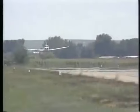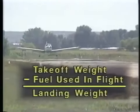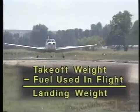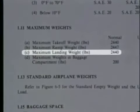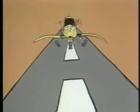An airplane also has a maximum landing weight. This weight can be determined by subtracting any fuel used during the flight from the takeoff weight. The maximum landing weight can also be found in the airplane's POH. If you operate your airplane above this weight, the shock absorbed during landing may overstress the landing gear or damage the wing support structure.